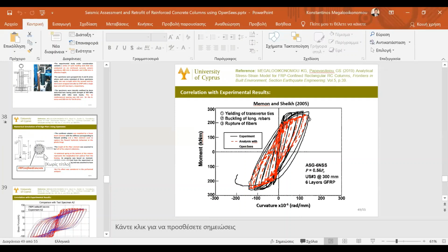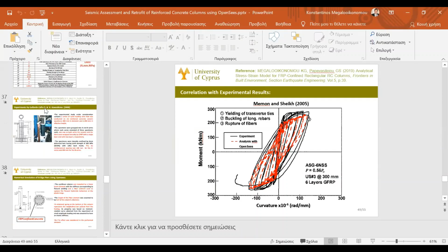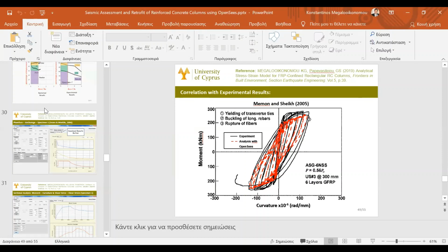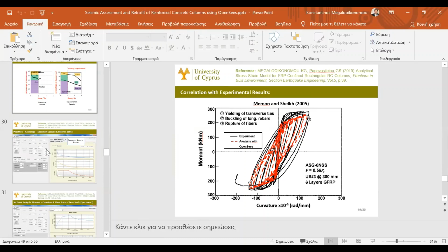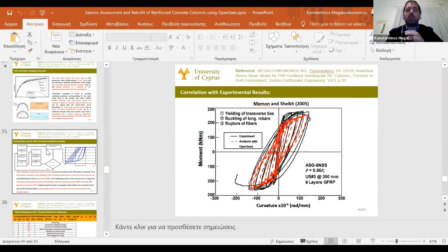Okay, I see now. In the material level, you also incorporate the shear deformation. You define them, and the cyclic constitutive law also reports shear stress and shear deformations. Okay, so I joined the presentation late, so I didn't follow the first part. I only attended partially. In the first part, is your model available in the form of a uniaxial material in OpenSees? Yes, FRPConfinedConcrete is available in both.